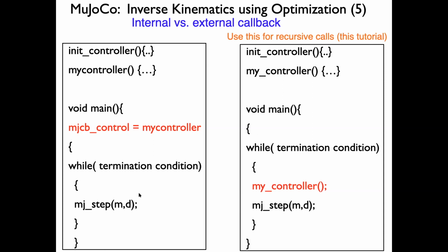So what that does is this. Let's say that we use the Runge-Kutta method to integrate the equation. Runge-Kutta calls my controller every time it wants to advance the simulation time. So in the case of Runge-Kutta, to go from t to t plus delta t, it has to do 4 function evaluations, or 4 evaluations of my controller. So you do them 4 times, and so my controller is called 4 times. That's one approach.